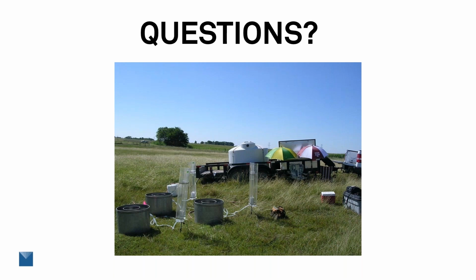So there are a bunch of factors that go into correcting that value, and then they ultimately give you the saturated hydraulic conductivity. The piece to be careful with in these corrections is that the component for correcting for three-dimensional flow is based on some intrinsic soil properties. And if you don't have a measurement of them, you have to essentially guess at what those properties are. And if you take a wrong guess, or if you pick the wrong value for alpha, you could wind up with an inaccurate hydraulic conductivity. So just something to be careful with.